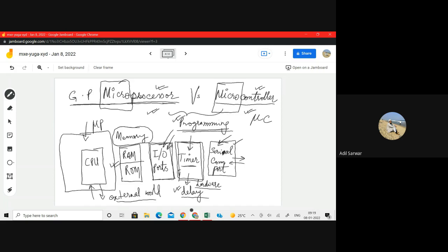So which one is faster? Definitely parallel communication is faster. But in some applications, say for long distance communication, we cannot go for parallel communication, because then we need parallel ports, pins and wires to interface the system to the external world, while we require only one wire to transmit and receive signals when using serial communication.